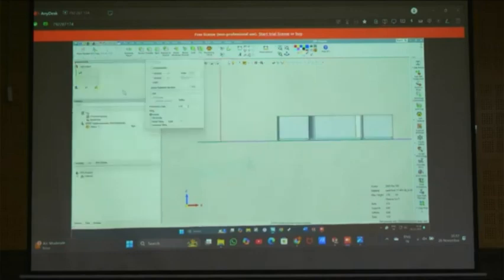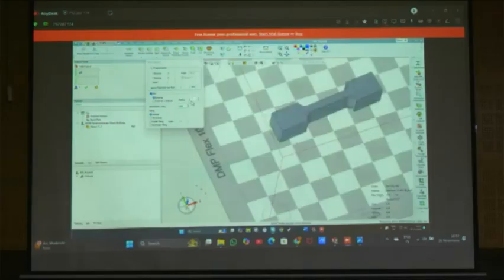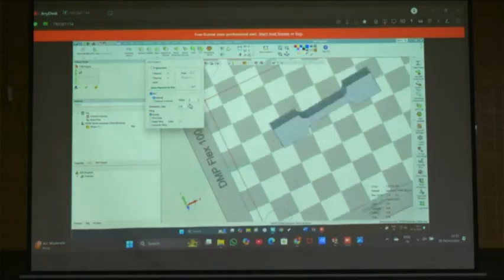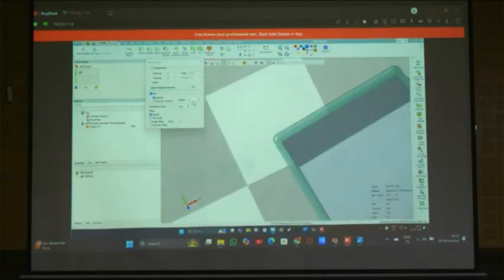Solid support. Yeah, skirt here it is there. Okay. Yeah. Since the height is 1, we can tweak this value. I will keep this as 1 since the height is 1, so that we can get the chamfered shape. See, we are getting this chamfered shape, right?